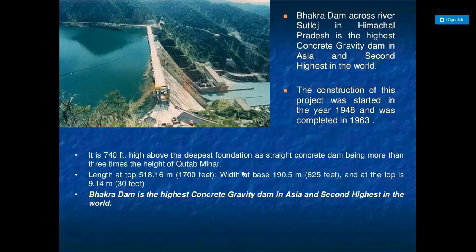The distance between the heel and toe is known as the base width. It depends on the height of the dam. The height depends on the nature of the foundation. If the foundation constitutes hard rock, the height may be more than 200 meters. Spillways are provided at the full reservoir level. The solid gravity dam resists all the forces on it by its own weight at the foundation. Therefore, a dam of this nature is to be selected only in such places where very competent and stable rocks occur. This type of dam is built in narrow to wide valleys.